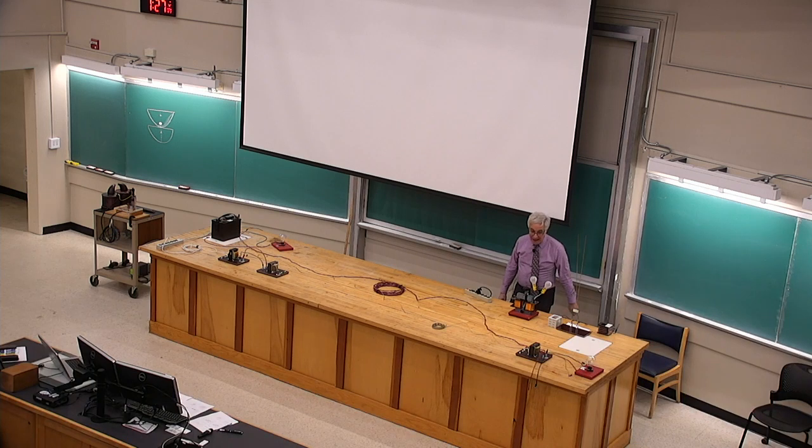The energy is bouncing off that electromagnet. This is what's called a reactive load. The power company is aware of things like this around its power network because they can sense that somebody's storing the energy for a quarter cycle and then giving it back the next quarter cycle. It does affect the power company, and they have to compensate for it in various ways. But other than that, not a big deal.